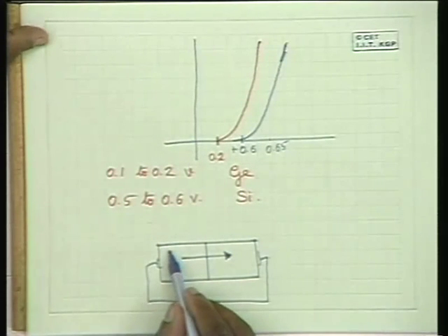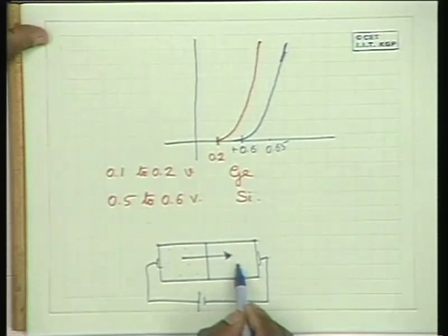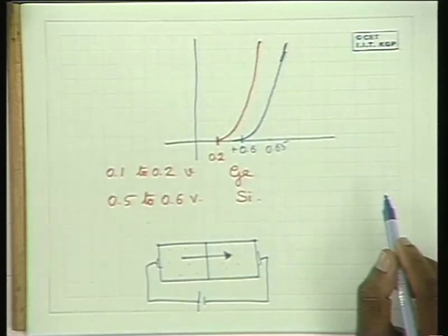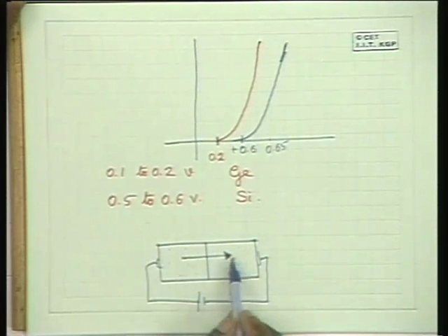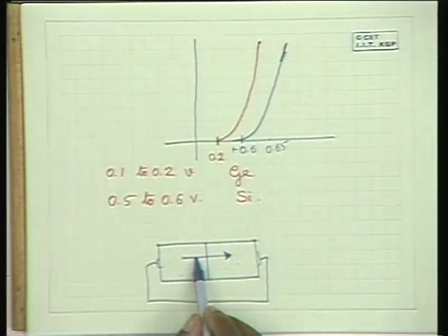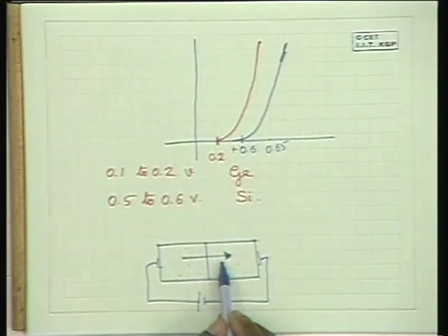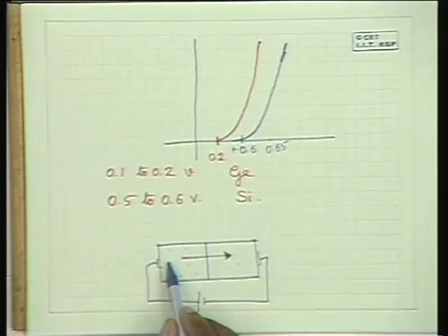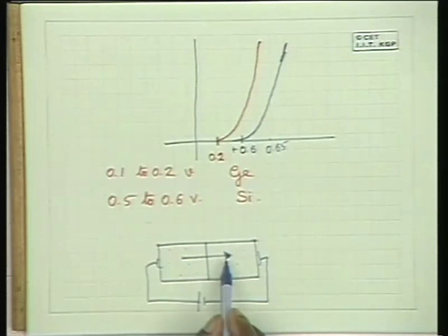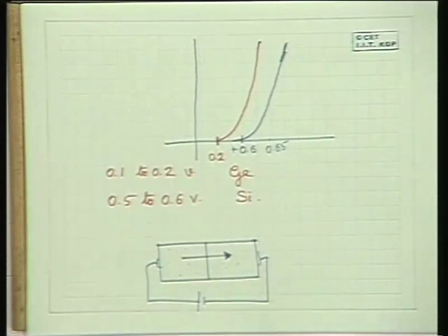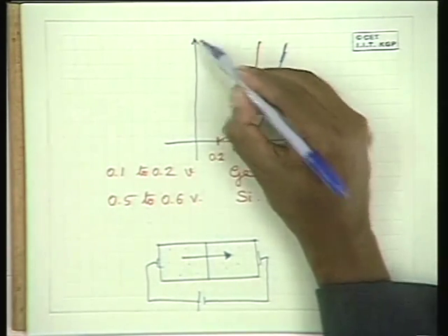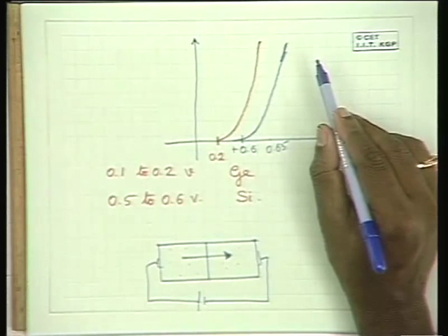And now, if the bulk semiconducting material exhibits some amount of resistance, which is true, because of that there would be some voltage that drops across the bulk material, and some voltage that drops across the junction. Therefore, the external voltage that is applied is equal to the bulk voltage drop plus the junction potential. Because of that reason, you have a slight increase in the voltage with increased current across the diode.